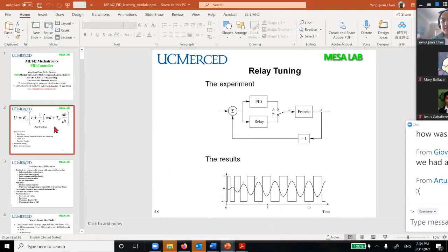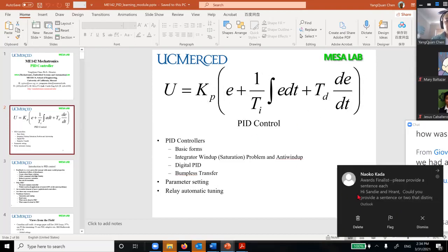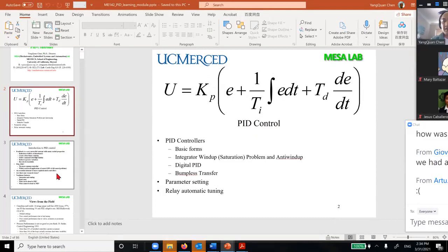So first of all, we have seen the PID control. We put a gain on the outside. Inside, this is called the integration time constant, and this is called the differentiation time constant. Remember that you have a dt in here, you have time, so you have also a time in here. So this is also in the unit of error. You have time in here, cancel the time, so you have a unit of error. So that's why they write it so that everything here is the same unit. Then you multiply by this. So this is the format.